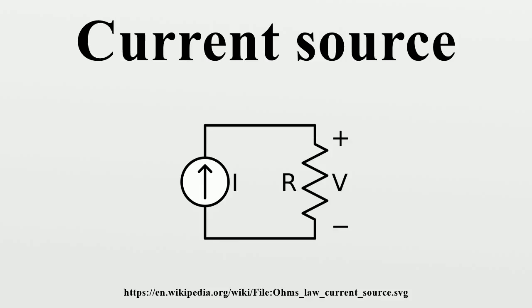They are often used in place of ohmic resistors in analog integrated circuits to generate a current that depends slightly on the voltage across the load. The common emitter configuration driven by a constant input current or voltage, and common source driven by a constant voltage, naturally behave as current sources because the output impedance of these devices is naturally high.